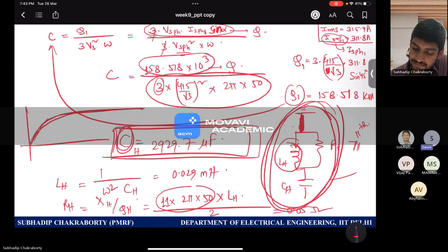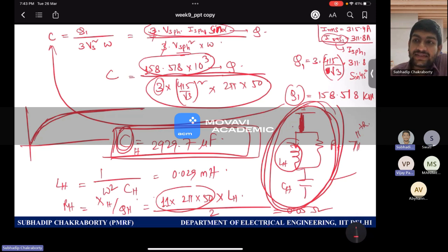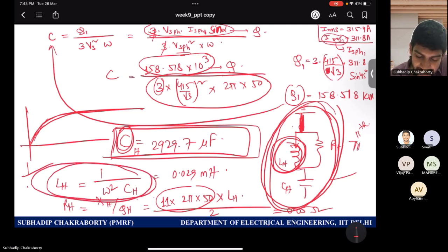That means, sir, for any frequency, the method for calculation of C remains the same. Because we are assuming the capacitance is providing reactive power support at the power level. That is its primary role. Whenever you are going to the higher frequency side, this inductor's role will start dominating. That's why we are putting in the resonance condition, right? 1 by omega square, that condition. Any one you fix, and the other one you have. How do we choose between high pass and single tuned?